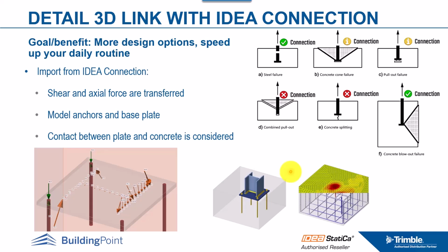So as you can see in this slide, in IDEA StatiCa Connection, as we said, you can check the failure of the steel operations like gusset plate, bolt, welds, or whatever we mentioned earlier. But once it comes to checking the concrete block, for example, concrete cone failure, pull-out failure, combined pull-out failure, concrete splitting, concrete blowout failure, these things together cannot be done in IDEA StatiCa Connection properly.